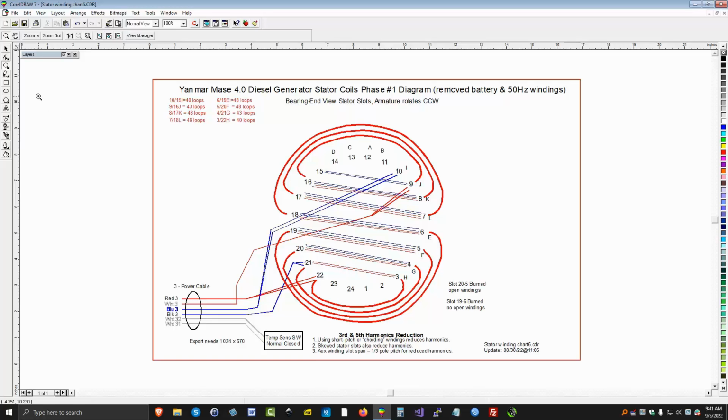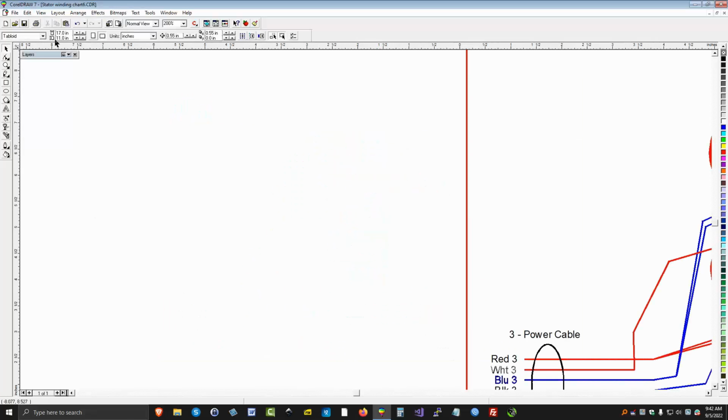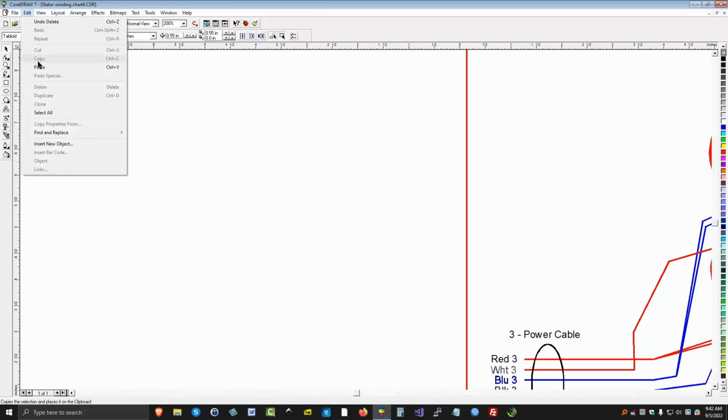Okay, we covered the important things in this lesson so far: the nudge, the duplicate, zoom in, zoom out, and how to edit, undo things you didn't mean to do, that you did by mistake. You can undo, or you can also repeat the last action. Whatever the last action was, it repeats. So if you do Control D, and the Control D, if you remember, does a certain offset right here, then you can repeat that if you want something to do the same offset. Let me show you an example of that. Let's go back here.